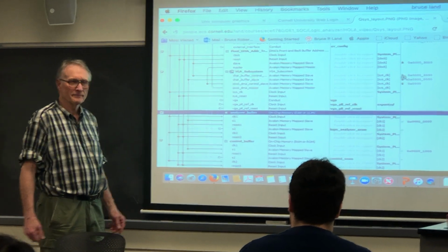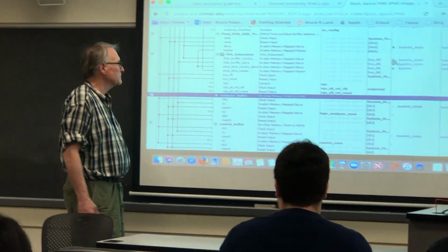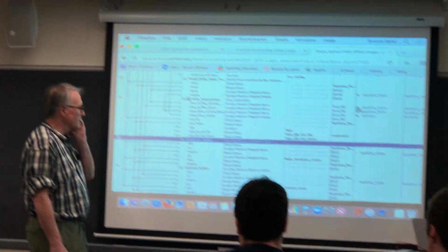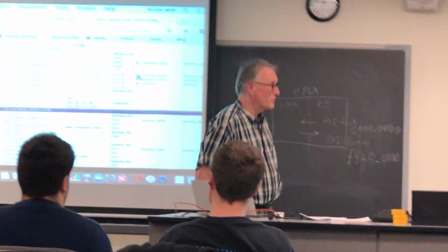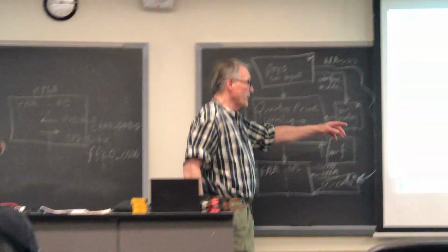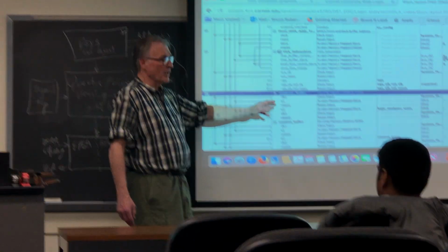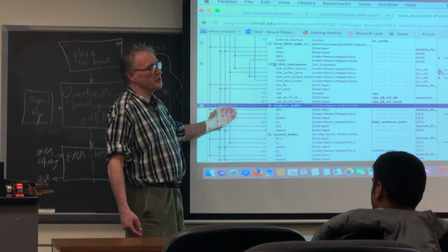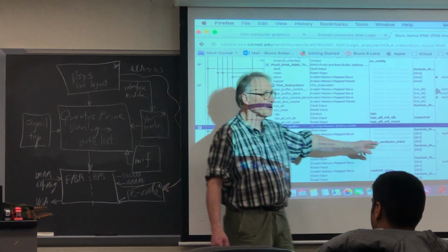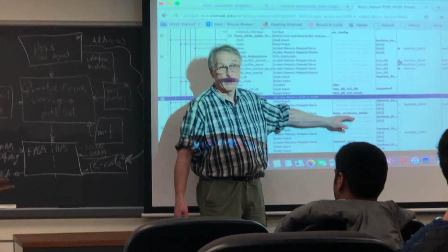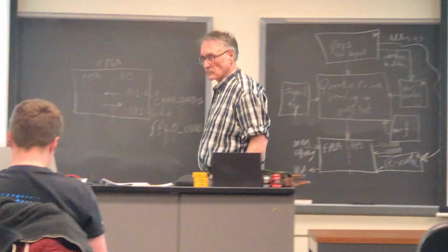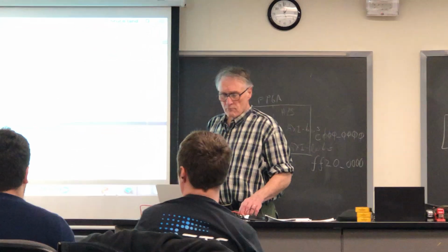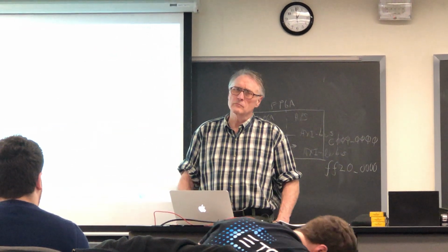I use it a lot. You can also make an extremely fast display memory by dual porting a memory block so that one side goes to the VGA subsystem and the other side goes to your GPU that you've just built. More questions?